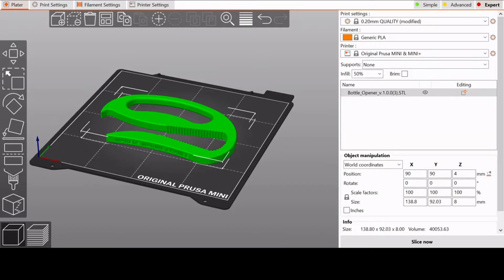Remember that using a higher infill percentage, up to around 50% or so, can give you really good strength in your print, while a lower infill percentage, around 20%, will give you a lighter product that may be a little bit less durable.